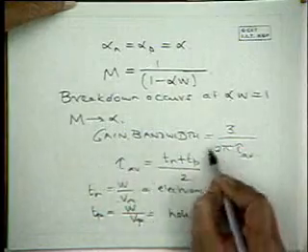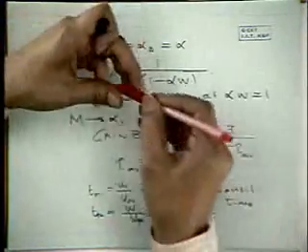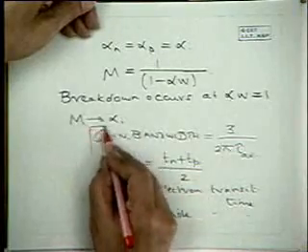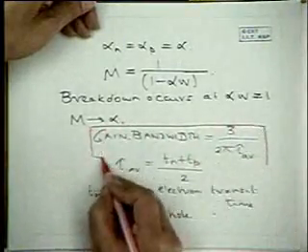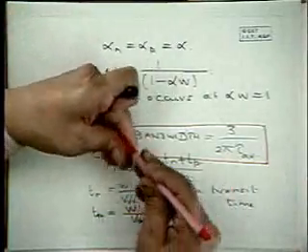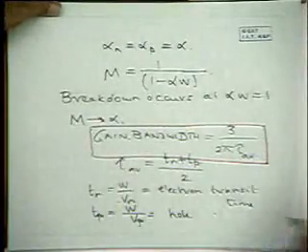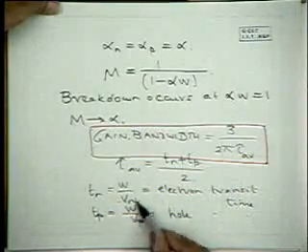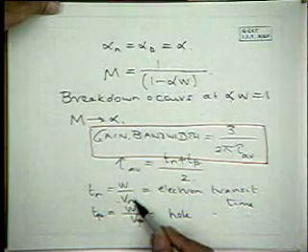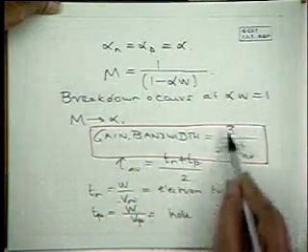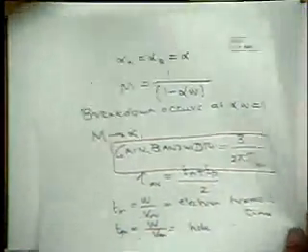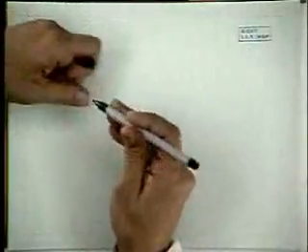So this expression is slightly approximate because we've taken M equal to infinity, but obviously we can increase the gain bandwidth if we can reduce W, and Vn and Vp are properties of the material. So if you have higher saturation velocity, obviously then this gain bandwidth will increase. Now let's get to the topic of noise.